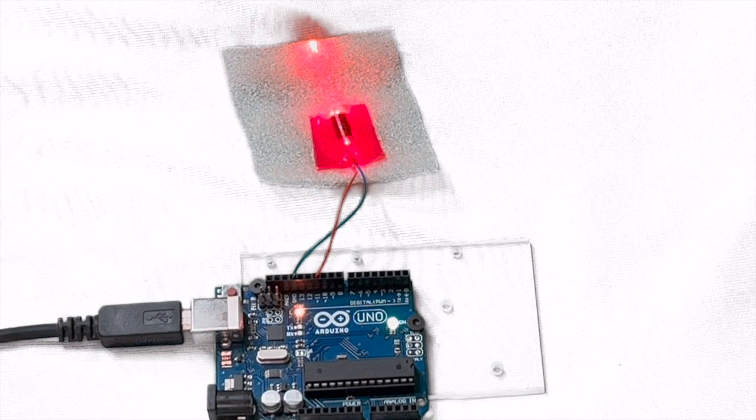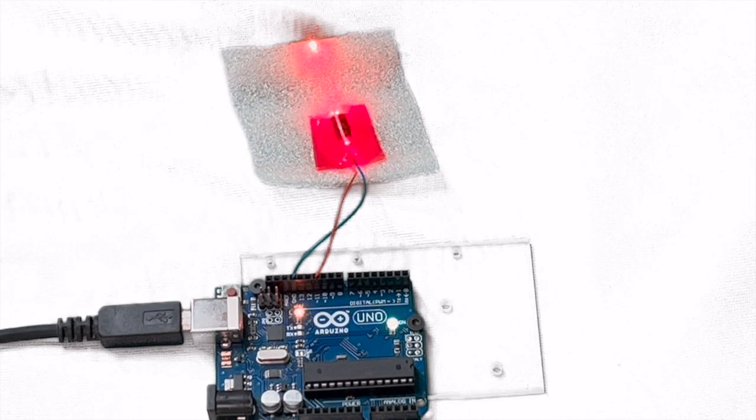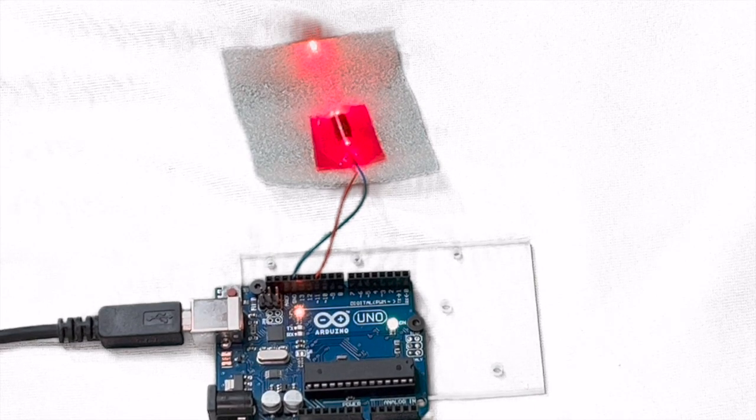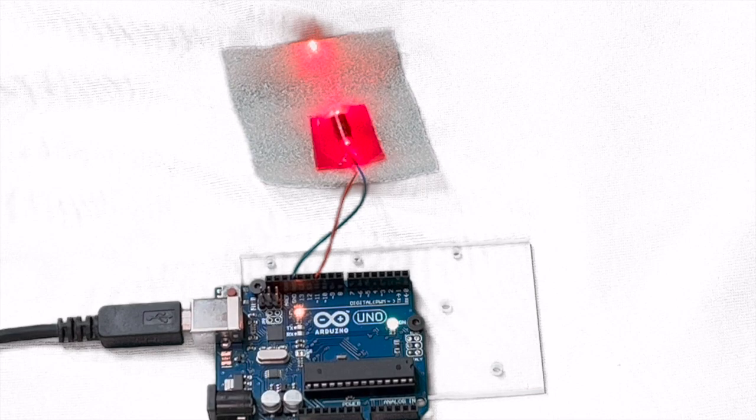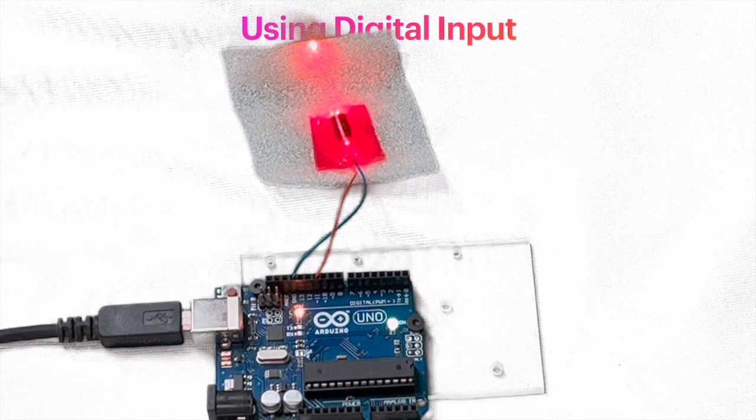You have often seen such a volume controller, where you have a single button which you push, and it changes the brightness, and eventually it reaches a maximum and then cycles back to 0 again, going in a round. So this is what we are going to do. For that, we are using one of the digital ports as an input and sensing whether it is low or high, and accordingly we will change the intensity of the laser.